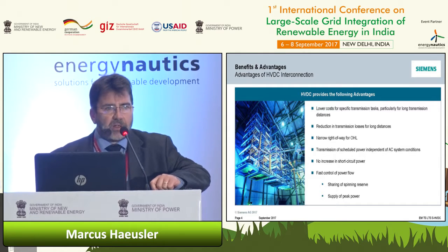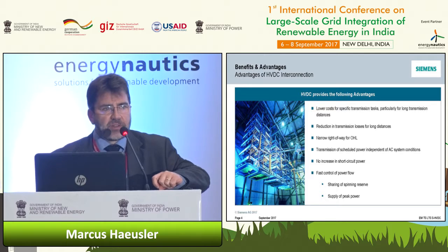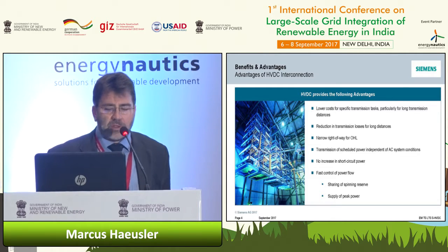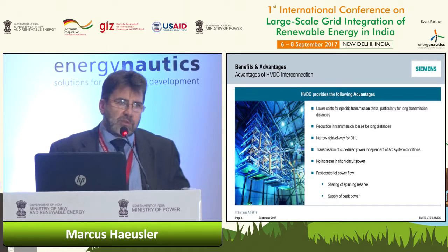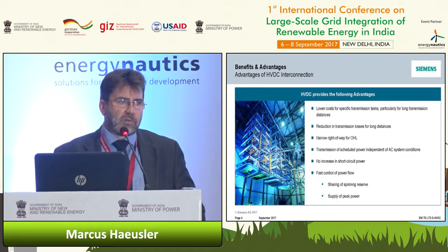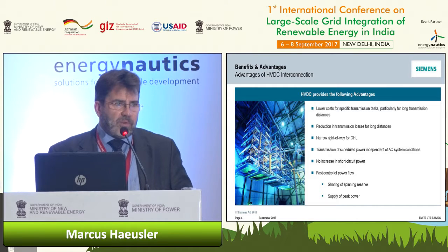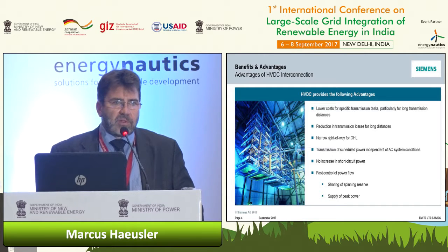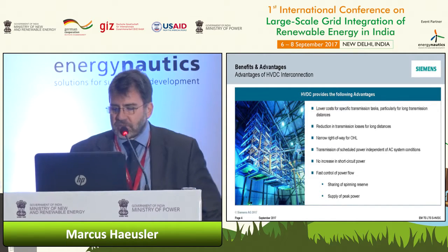And finally, different systems, as I mentioned, and this is also used in India, back-to-back systems can be used not to interconnect different AC systems directly, but to exchange power without increasing the short-circuit power. So the existing power infrastructure can be further used, even if we have a larger number of generators in the same nodes.